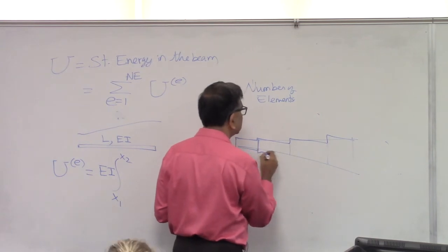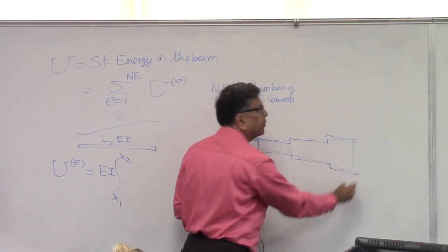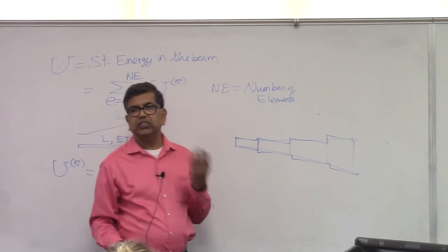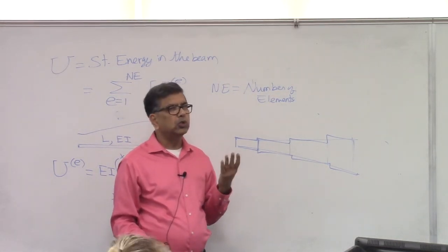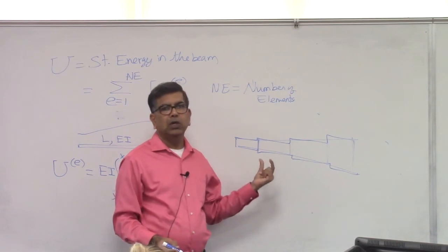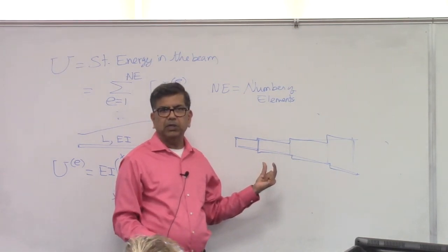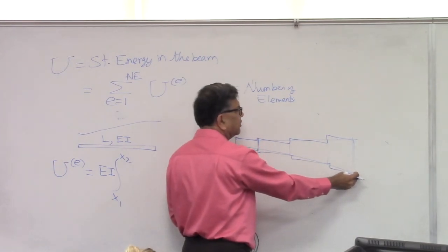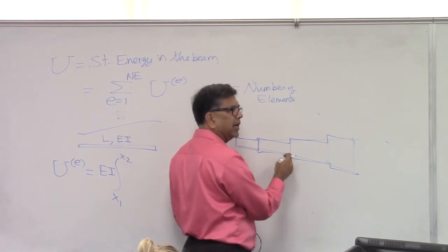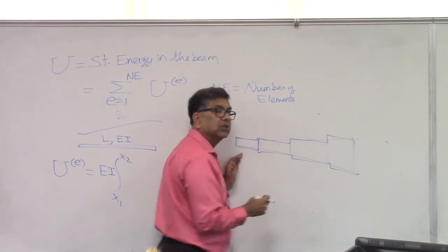So you make it a stepped bar. In finite element, you can solve only a stepped bar. You cannot solve a tapered bar. Now that tells you how short or how long the element should be, isn't it? Because if you try to model the whole tapered shaft as one element, you are making a gross approximation, because you'll be using some average diameter, which is not good.